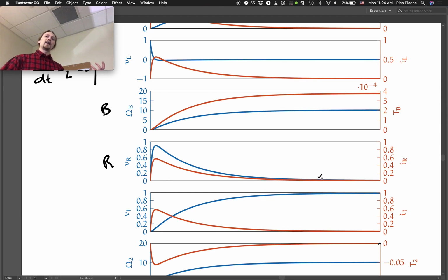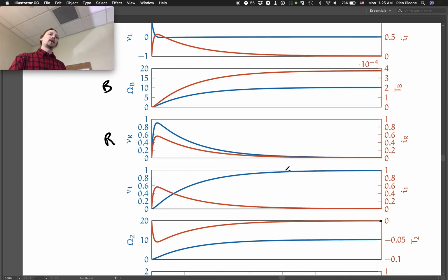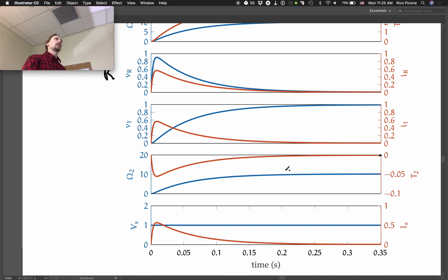But that's going to die off because when you get close to steady state angular velocity, we don't have a lot of current flowing. So we don't expect to be dissipating a lot of heat in the windings. So that's good. While the bearing started out not dissipating a lot of heat, it ended up dissipating more heat because we've got a higher torque here. The resistor has exactly the opposite characteristic, where at the low speed, high torque situation, it was flowing more current and heating up more. So we'll look at that a little bit more in the power flow graphs, and that'll help us there.